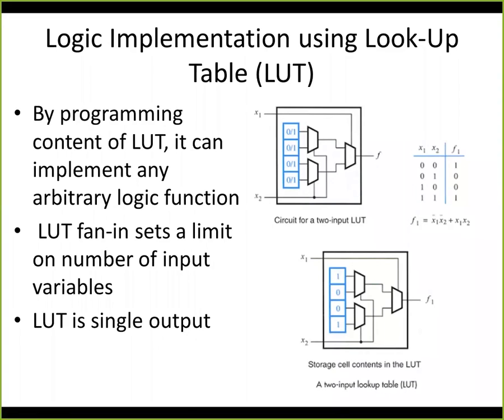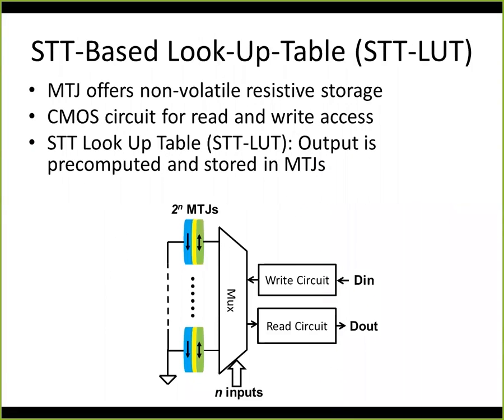So we use the lookup table-based implementation of logic circuits in order to realize combinational circuits. And that basically is by programming the content of a given lookup table. We map the truth table of the desired function into it and therefore realize the function. So this is the way we are going to use spin transfer torque technology for logic implementation.